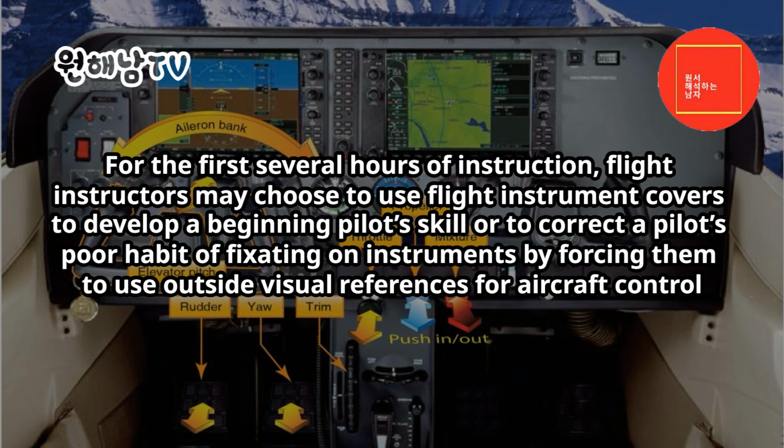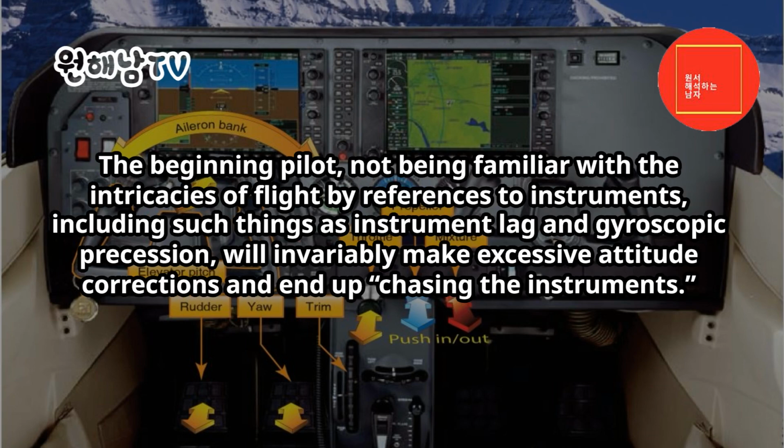For the first several hours of instruction, flight instructors may choose to use flight instrument covers to develop a beginning pilot's skill or to correct a pilot's poor habit of fixating on instruments by forcing them to use outside visual references for aircraft control. The beginning pilot, not being familiar with the intricacies of flight by reference to instruments, including such things as instrument lag and gyroscopic precession, will invariably make excessive attitude corrections, and end up chasing the instruments.